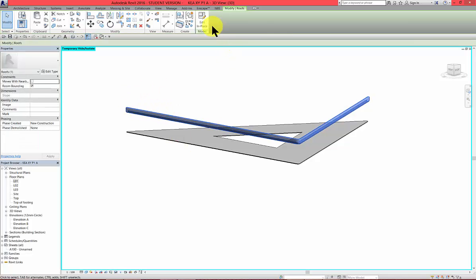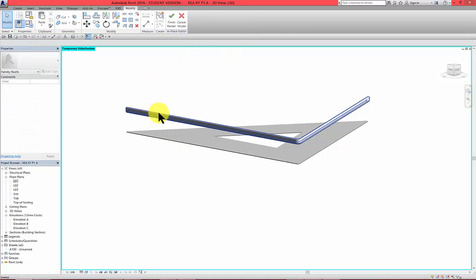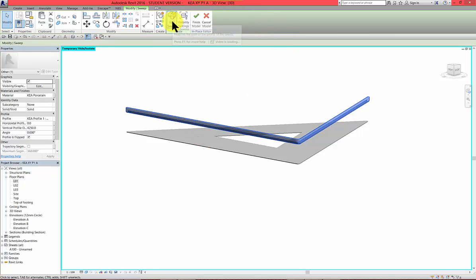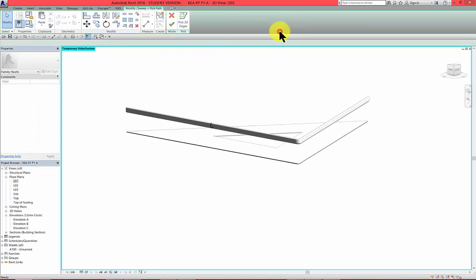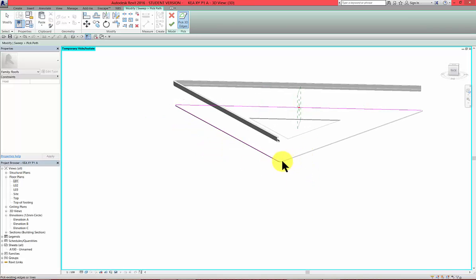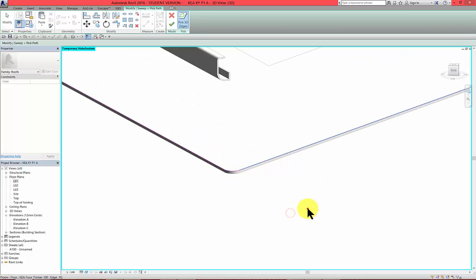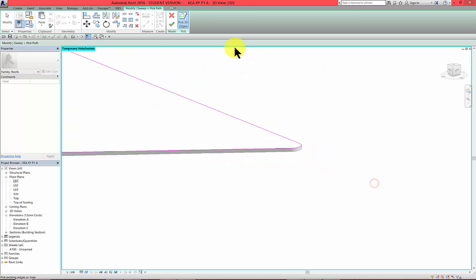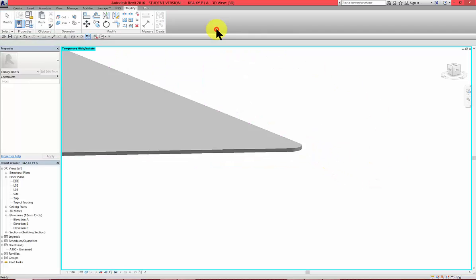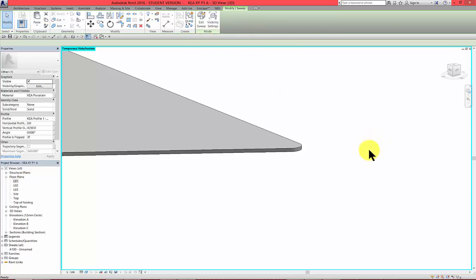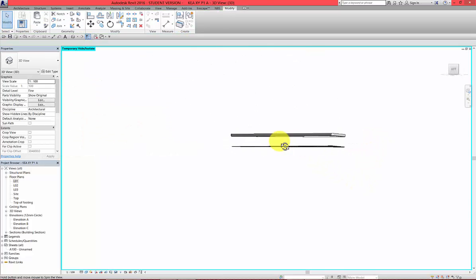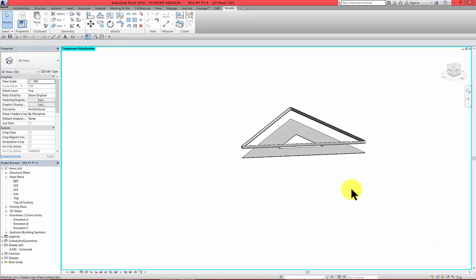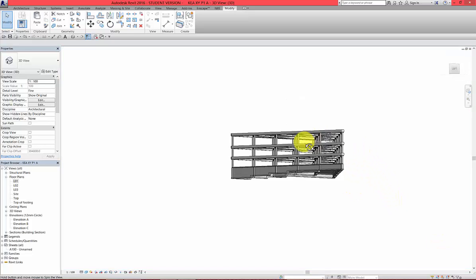If that works, we can edit this again. So select it, edit in place, then select it again, edit sweep, pick path, pick 3D edges, and then we can finish the path going around, then finish it, and finish this. If this is done, HR to reset.